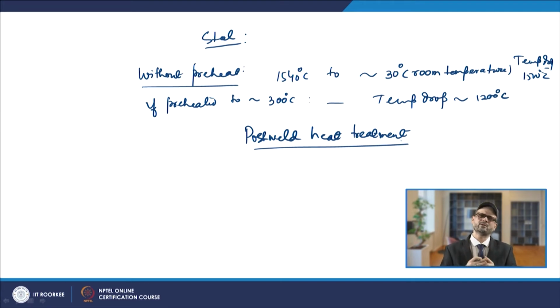But when we look at the post weld phenomena, there will be chances of the formation of residual stresses while cooling. If the residual stress levels are high, that may lead to a decreased service life of the component, so the welded component may fail. So post weld heat treatment is mostly for stress relief treatment.